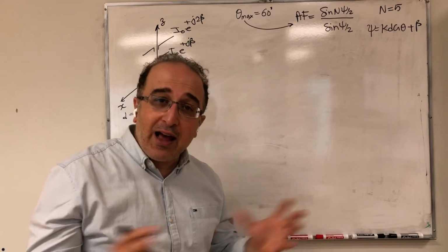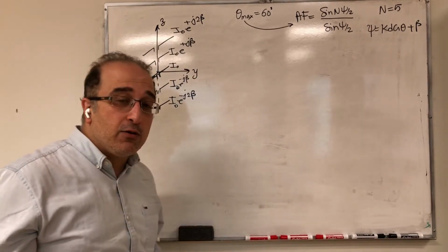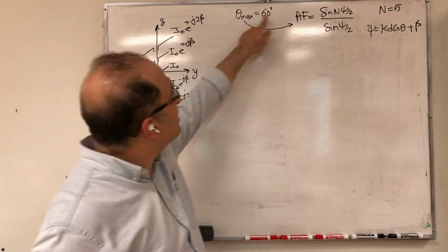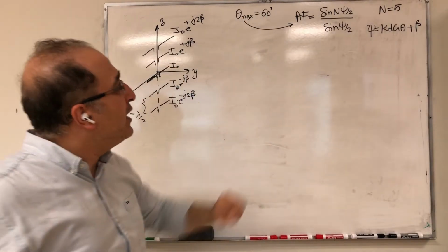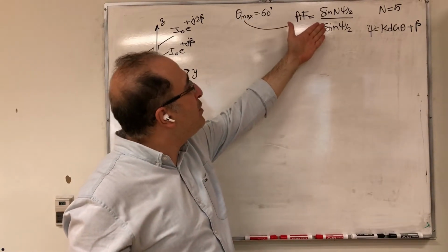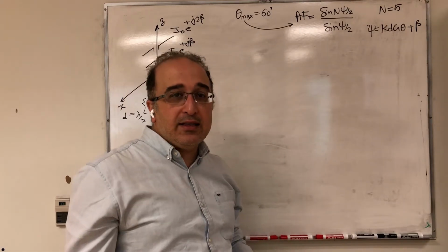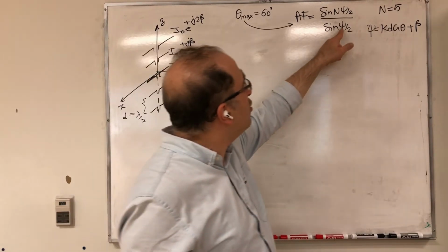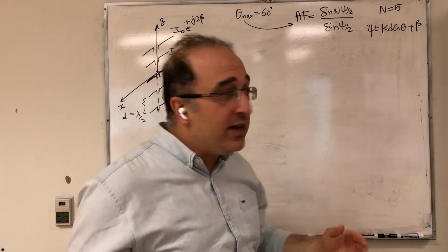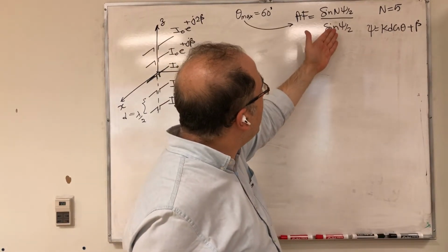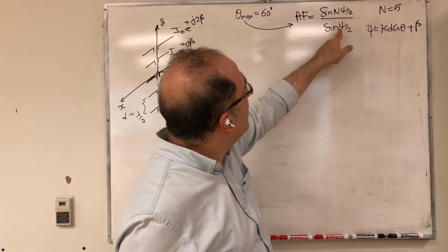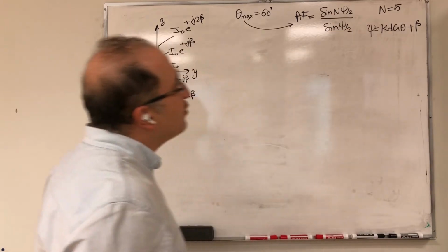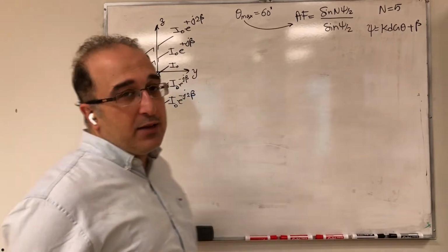Till now, we don't have any discussion on the particular choice of antenna. So this max refers to the array factor. And we know that the array factor can be maximum when psi is 0, because if psi goes to 0, that means they're all in phase, or mathematically, the limit of this AF goes to N, which is 5, and it becomes maximum.